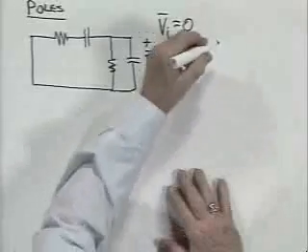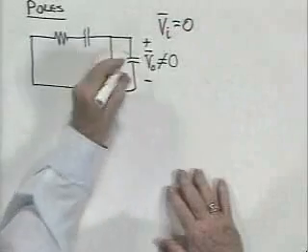And the only possible interpretation of that is that those frequencies must represent the natural frequencies of the network, and the responses, we see just one here, V sub O, but I could label any other voltage or any current in the network, and it would have the same frequency dependence. The responses are the unforced natural behavior of the circuit. So in circuit terms, we can say that the time function here,